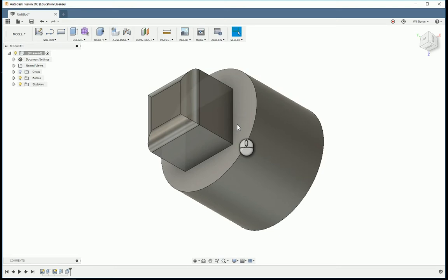And whenever you're designing a part, try and account for, I like to call it the wiggle room. If you're in millimeters, which I would recommend everybody doing, it gets a lot easier, because everything in 3D printing is millimeters. That aside, in millimeters, I like to leave 0.5 millimeter to a full millimeter of free space around an object. So if I was making a hole to fit this square head, I would leave 0.5 on every single side. 3D printers aren't precise enough, and the material itself will shrink when you actually print it.